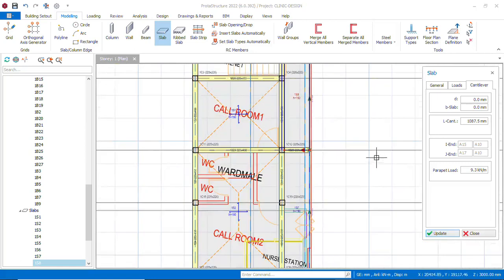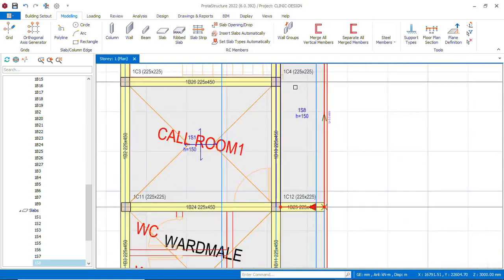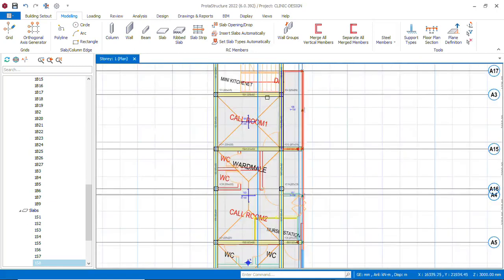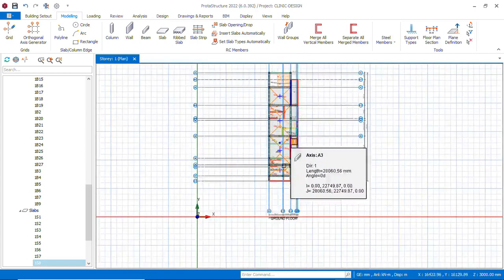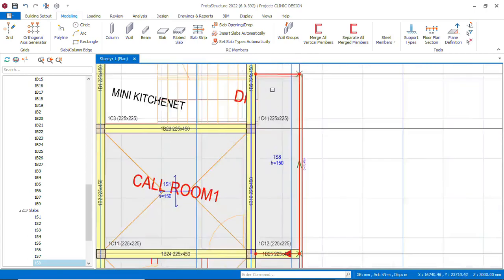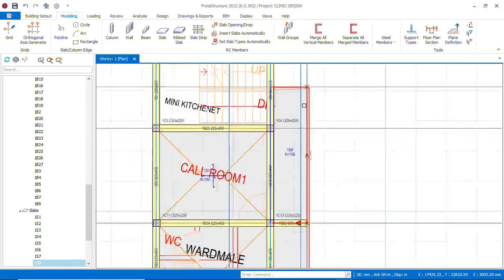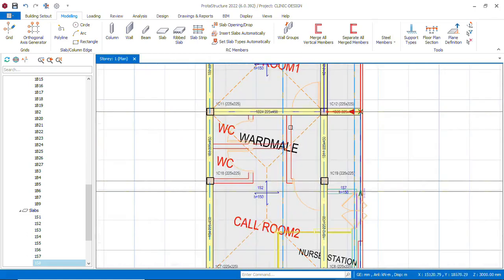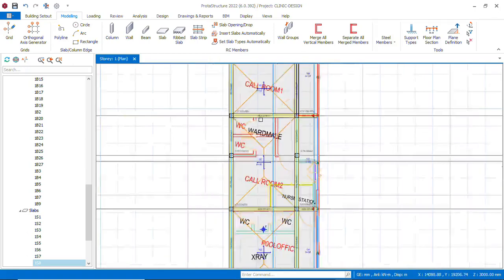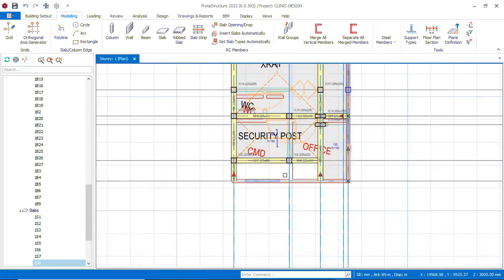So now you also have a wall here, but when you land here, you come within this and enter the door from here for access. So here we create a line load, here, and in this here there is a wall on the slab. We'll create line loads at all these places. Create our line loads. Then let's finish with the slab.